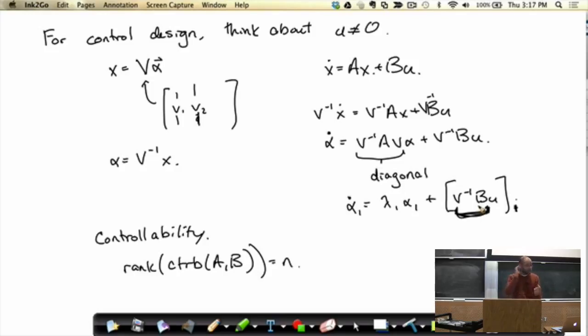And you might think that an underactuated system is an uncontrollable system, but you would be wrong. Right? In fact, we're going to see again and again here that the Acrobot, for instance, trivially underactuated, okay, is perfectly controllable in its linearization at the upright. You do have enough control authority to drive the system back to the origin, even if it gets knocked away. But it requires an interaction of the different degrees of freedom to get there. You don't have instantaneous control back, but you can find a path back.